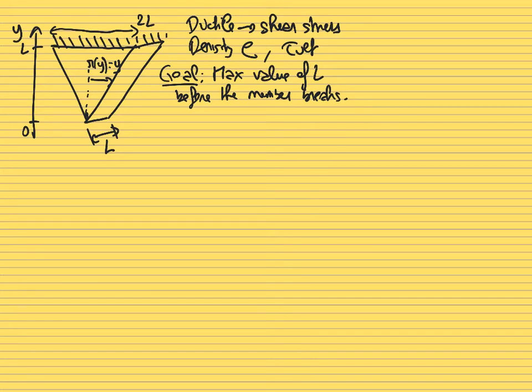So the beginning is just a conventional axial load problem. We just need to calculate the internal load by using the method of sections. So the step one is to identify the unknown. In this case, you have a fixed support on the top that is going to apply a resistant force that is going up, that we can write N naught. And the first thing will be to find the value of this resistance N naught. And for this, we have to write the condition of equilibrium for this beam.